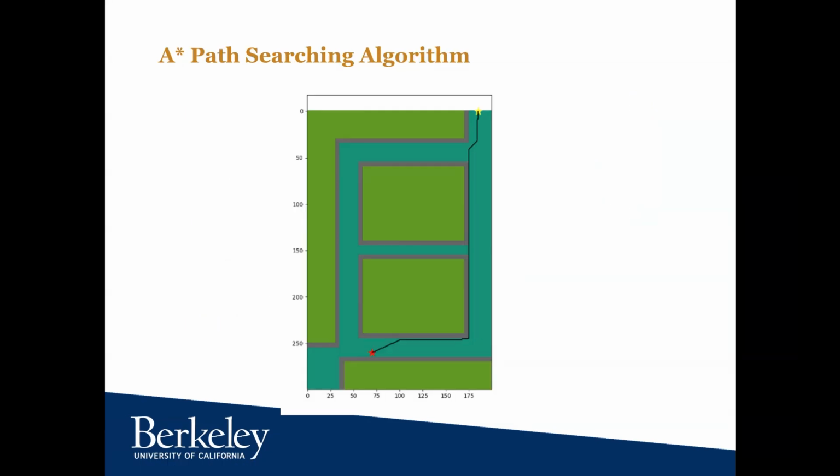The A-star searching algorithm is a commonly used path-finding algorithm because of its simplicity and speed. Though used alone, it does not determine a dynamically feasible trajectory. We use A-star to provide an initial predicted trajectory for reducing the large number of repeated computations caused by complex maps. We first grid the map according to the true size and create nodes. The A-star algorithm will calculate the cost of each neighboring node from the start point, and the final cost is the sum of the cost of each step.